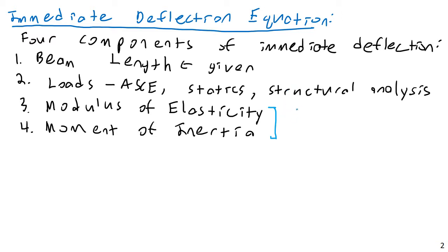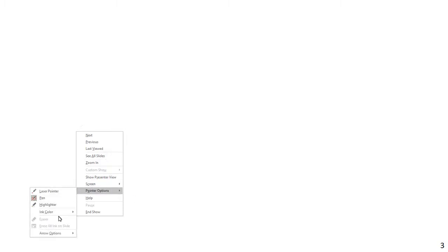And so we need to use ACI 318 in order to calculate each of these things, or determine each of these things. So the first thing I want to do is look at modulus of elasticity. This is the easier of these 2 things. So modulus of elasticity, concrete being a rather complex composite material does not have a single modulus of elasticity. It has a more complex relationship. In other words, it doesn't have a nice linear zone for the modulus of elasticity where the stress strain plot remains linear for a long period of time. It has a continuously changing slope.